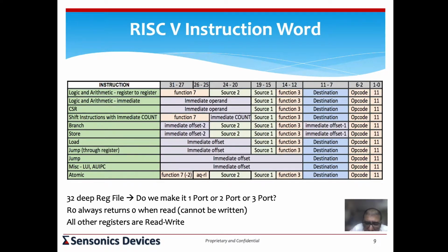Should we have a register file with only one address mechanism, that is, a single port register file? We can do that. That will be a compliant RISC-V. It'll work slow. It'll need 2 cycles to fetch the 2 sources, then it'll need 1 cycle to write the destination. Even if you're able to do the computation in 1 cycle, you'll need 4 cycles to do this, and you can't pipeline. But you can do it. You can make a very, very small processor using that. I believe somebody has also done that. I vaguely remember seeing something on the web. Somebody has done that, I think. You can make a very small processor, maybe under 8,000 gates.